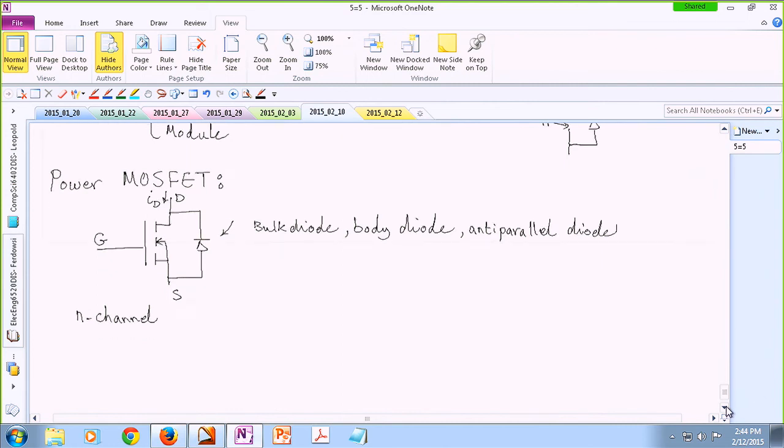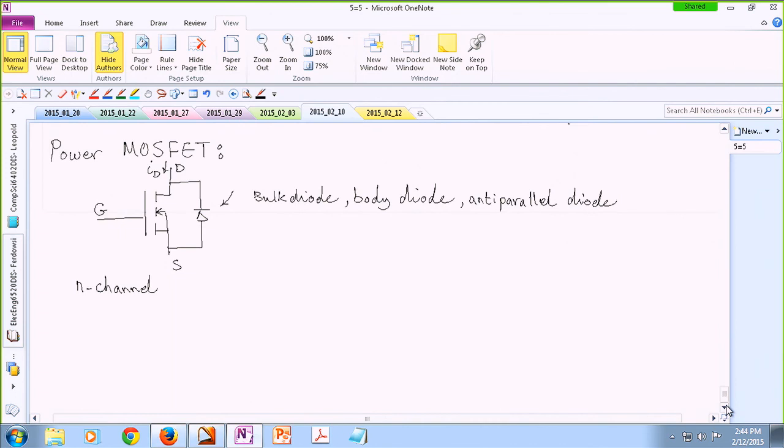So in terms of IV characteristic, this is the current of the drain versus the drain to source voltage. Okay. So if the device is off, it can actually block some positive voltages to a certain point till you reach VDSS, and the device breaks.